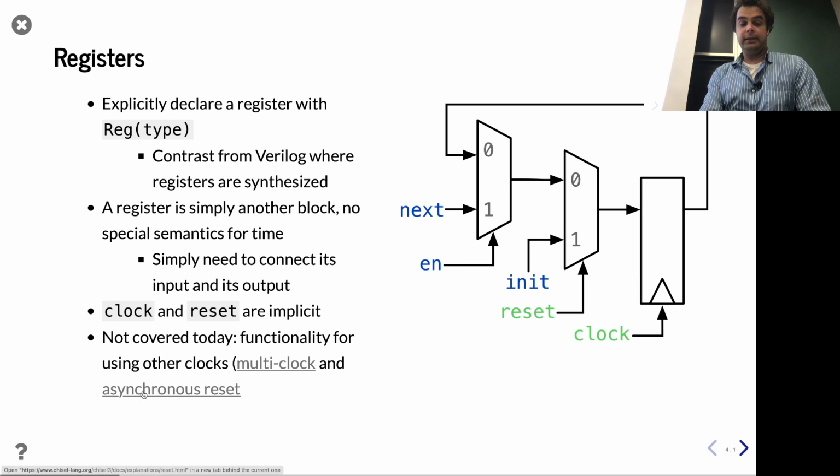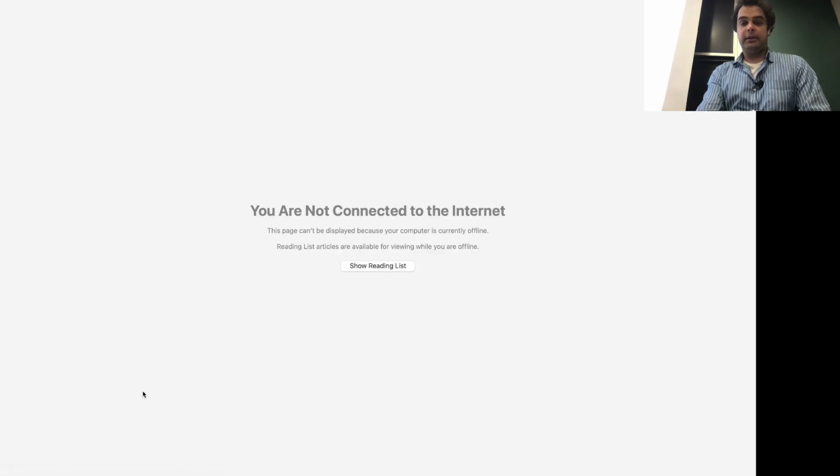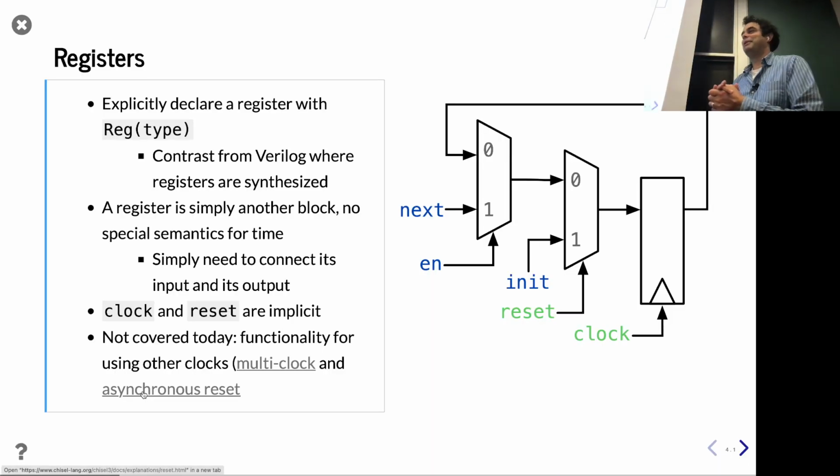So we go ahead and click on that link, and we can see the, oops, Wi-Fi come back to bite us. But other than that, you can see there's a little bit of syntax that does it a little differently. When it comes to multiple clocks, you actually mark the scope for the other clock domain. Like, this is clock domain A, this is clock domain B, and you can describe that. And you're supposed to use special devices to go between clock domains.